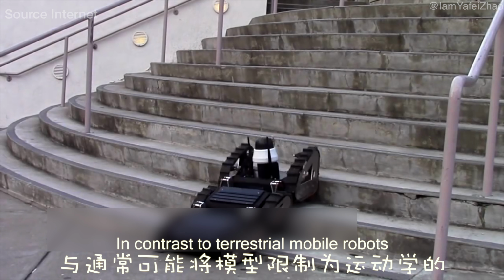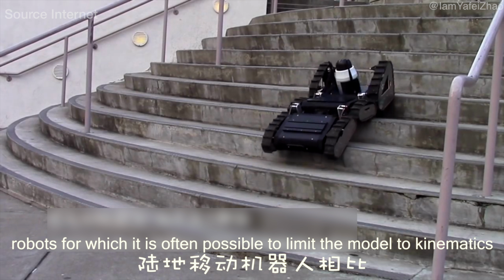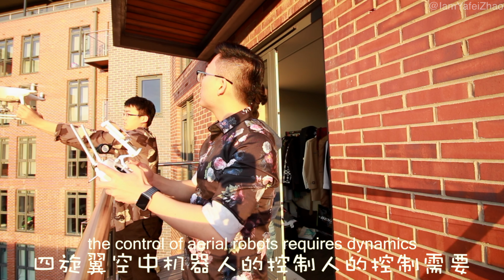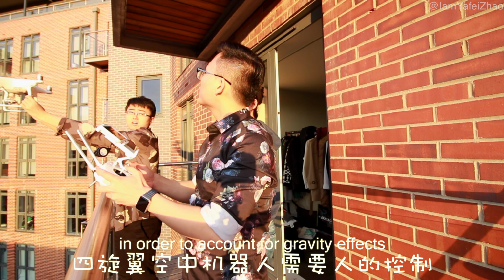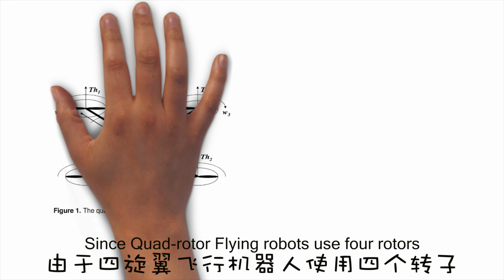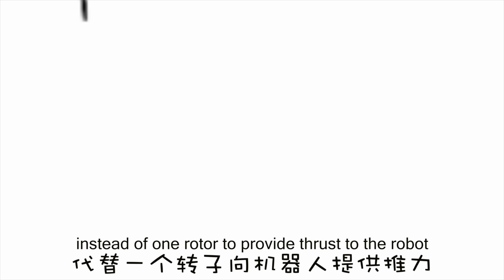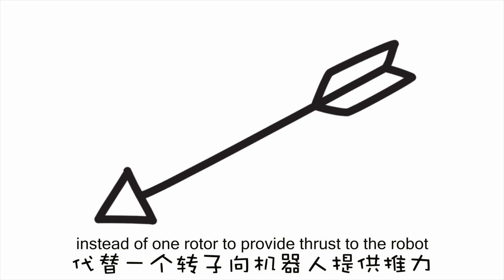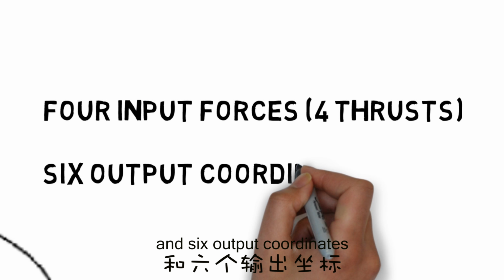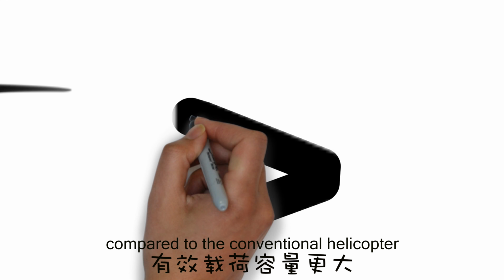In contrast to terrestrial mobile robots, for which it is often possible to limit the model to kinematics, the control of aerial robots requires dynamics in order to account for gravity effects and aerodynamic forces. Since quad-rotor flying robots use 4 rotors instead of 1 rotor to provide thrust, it has 4 input forces and 6 output coordinates. Thus, the payload capacity is larger compared to the conventional helicopter.